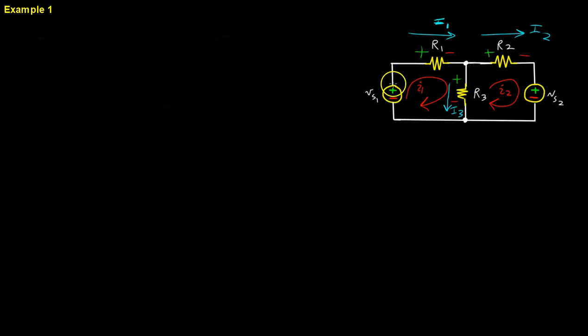Do keep in mind that a branch current is a current flowing from one particular node at a particular potential to another node. In this case it's going from this node defined as VS1 into some other node. We can call it VX, for example. It's a different voltage because there's some drop across R1. I2 is going to flow from this node through VS2, and I3 is going to go from VX through the ground node here. We can call that ground. Okay, so having done this, we can go ahead and see how we can actually do the mesh analysis.